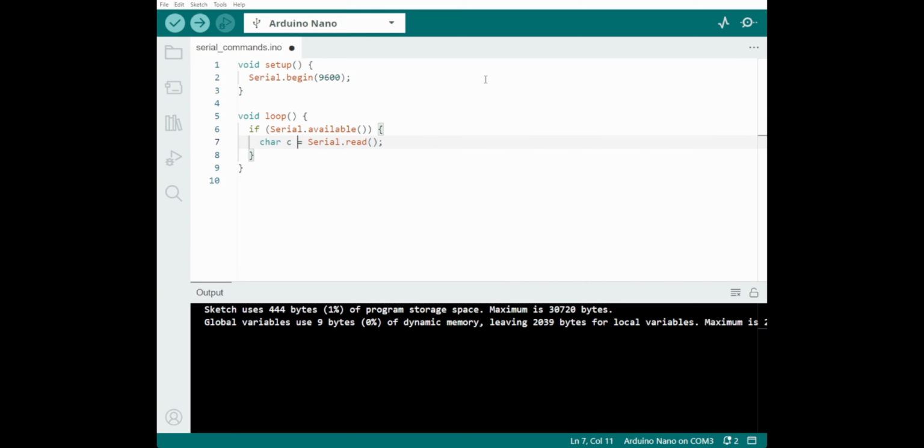That'll read us a character. And you go, brilliant. What do you want to do with it? We need to put it somewhere because let's just say I want to send the command ready, question mark. This needs to be able to pick up the characters and say, oh okay, he's now sent us a string ready. So we need to put them somewhere.